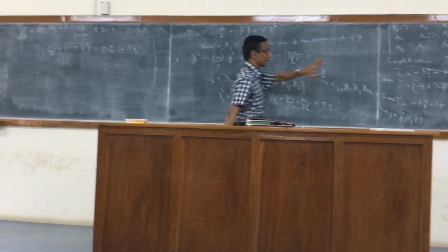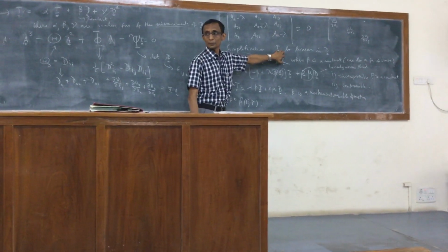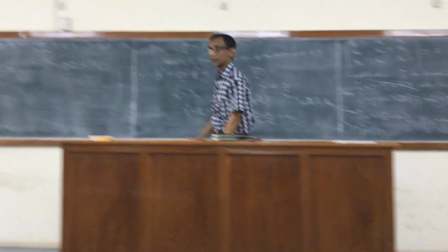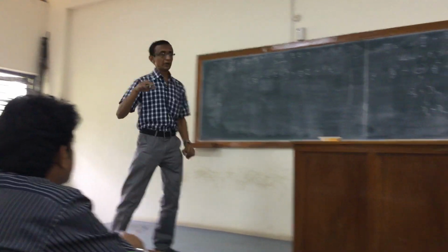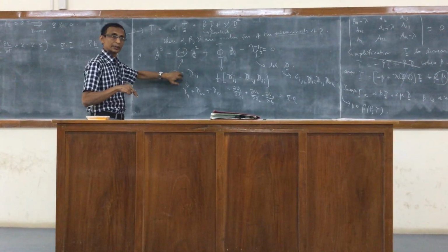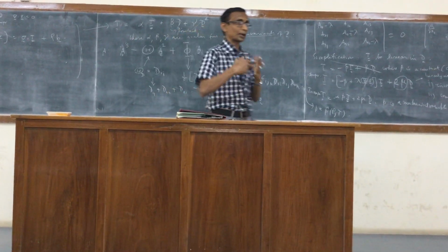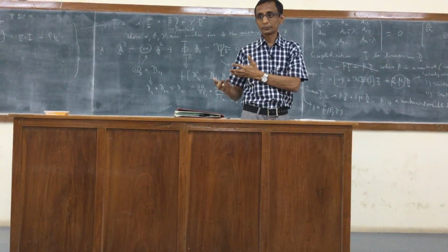If I leave it like this, then it's not the most general form, because alpha can depend on an invariant. For a linear fluid, the only linear invariant associated with D is the trace. So it can depend on the trace. So I am just multiplying it by a constant coefficient and introducing it in that way.